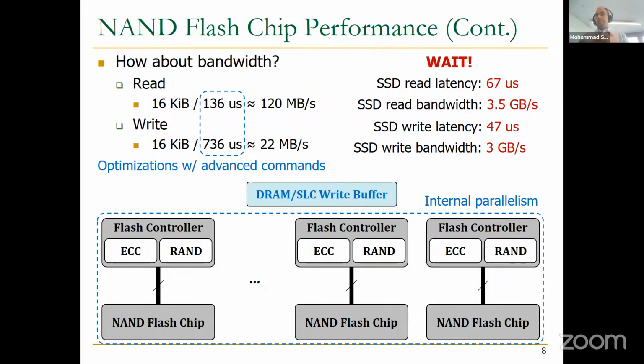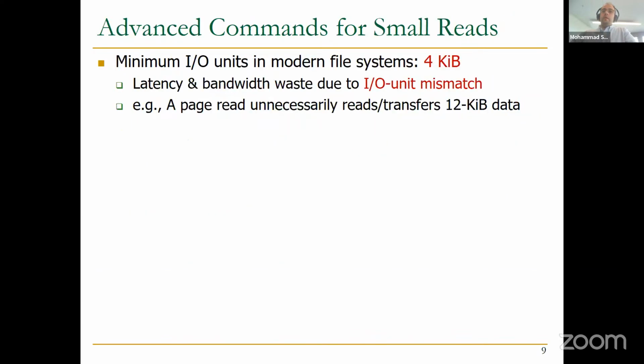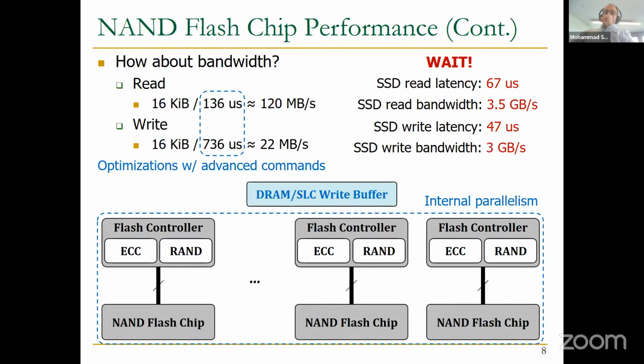With that, they can have a much larger write buffer because they don't have the problems of DRAM, that DRAM is volatile and we need to back it with enough capacitors to make sure that we have enough charge to do the de-staging of the buffer. So basically with this write buffer, we can heavily improve read and write operations as well.